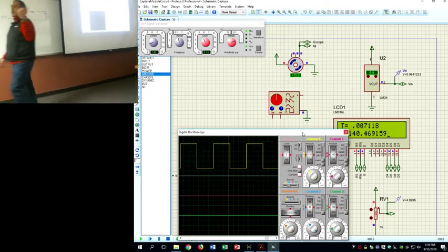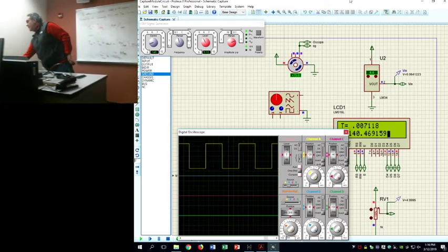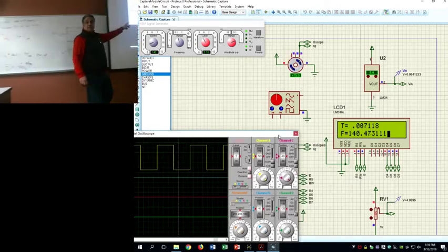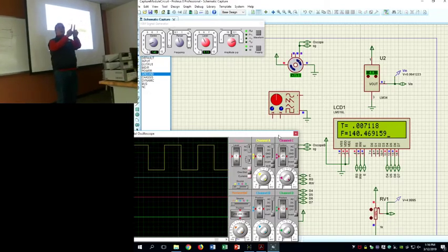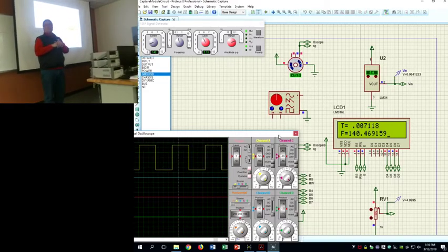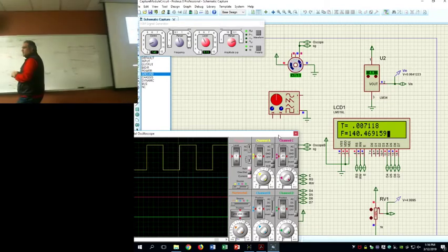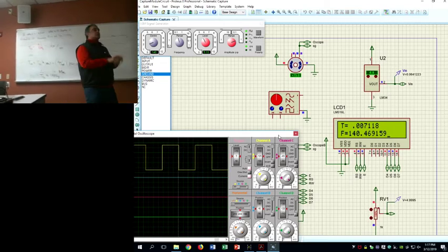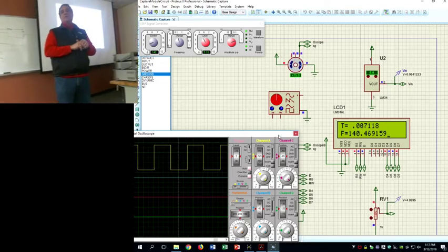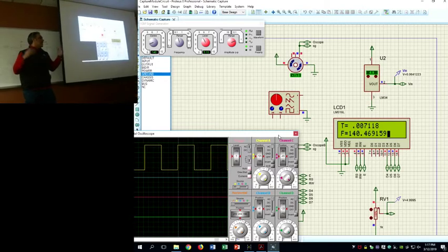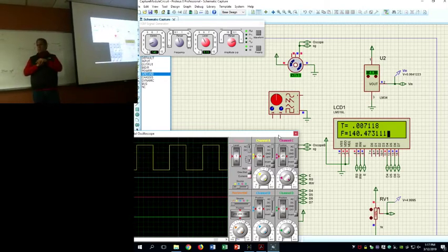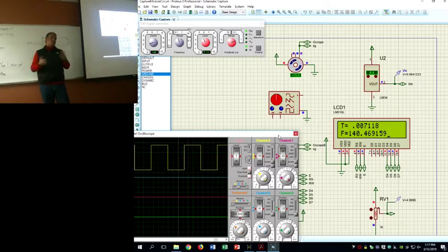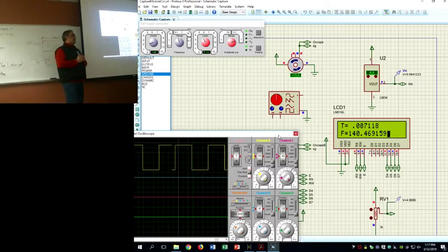Right now, this motor, I just put 5 volts into it for the heck of it, and it's running right now at 140 hertz. What that means is that whatever is coming in there, those little pulses are showing up at about 140 hertz. So there is right now about 7.118 milliseconds between reflective spots coming out of that encoder. That's what that means. You can buy any kind of encoder, but the beauty behind it is that now I have a micro that costs under $5 that gives me the ability to tell speed.